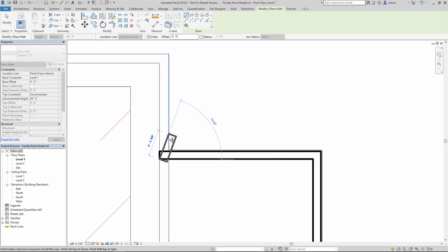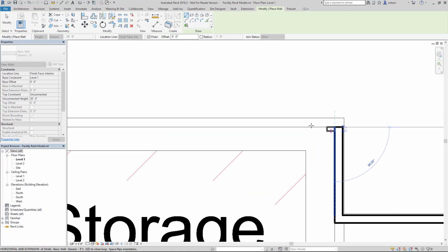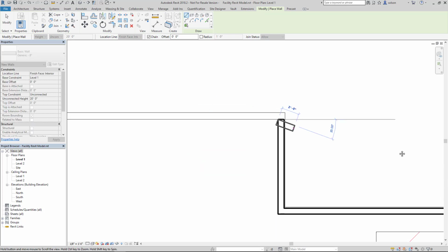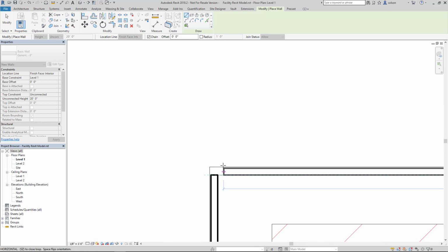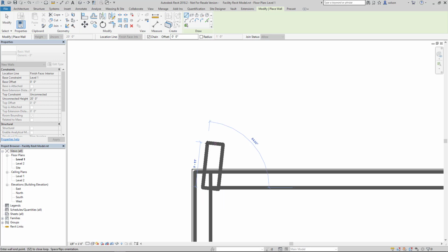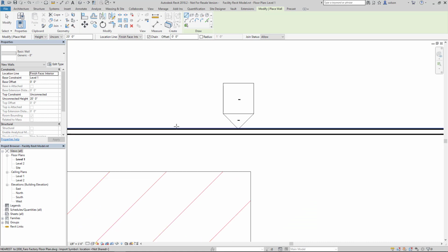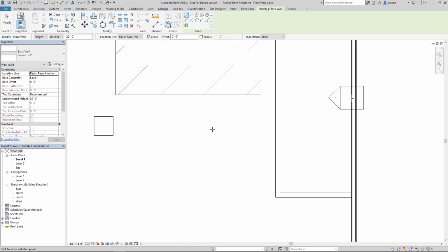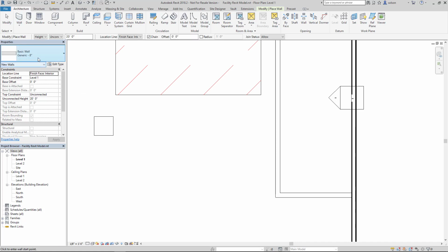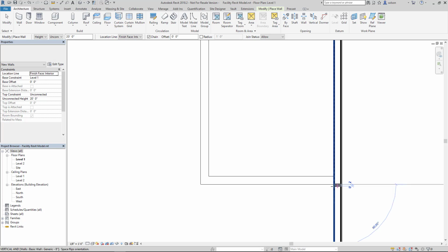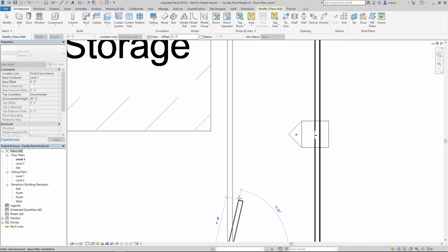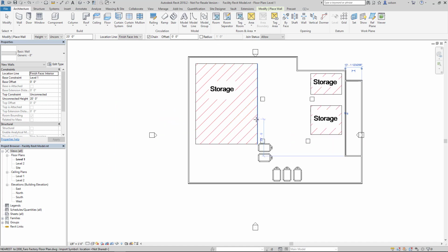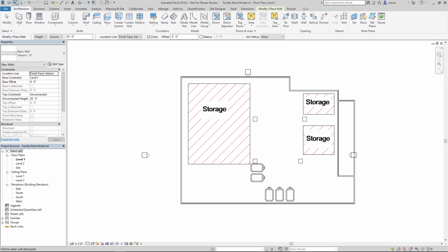I'll go over to here. Can come up. In this case, I'm going to click on the end of my other wall and escape to get out of it. You can see that Revit is really smart, and it ends up cleaning up a lot of those corners for me. Now, there is another interior wall here that I'll have to replicate as well. So go back to Architecture, Wall, still using the 8-inch generic, still using the right line location. And I'll snap into here. And now I've got my facility all set up and created. Let's go ahead and save this.